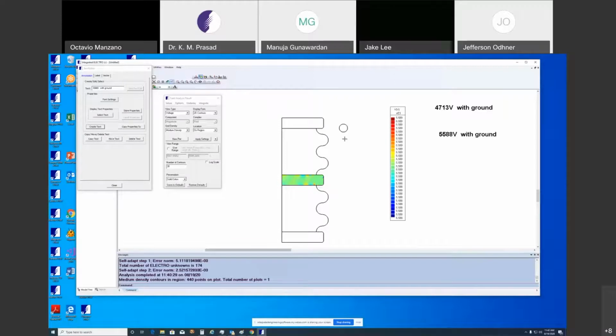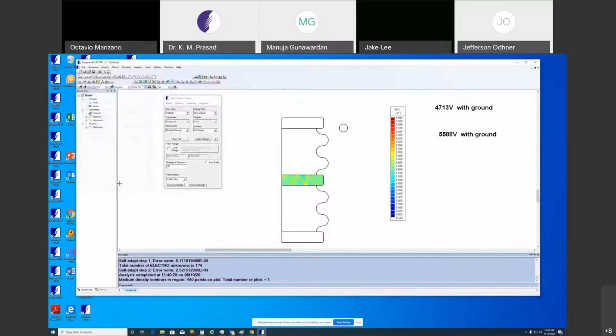For those kinds of cases, we should turn on the grounded voltage sources switch. If your model is small and you are operating with a battery, with one high voltage and another reference voltage, nothing to do with the physical ground, then you have to disable that ground.